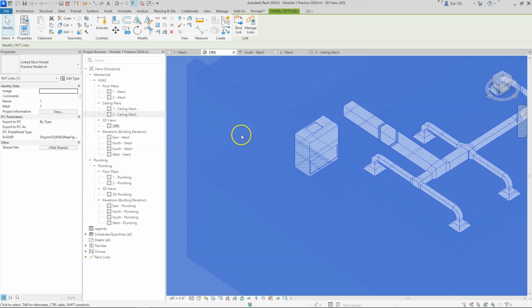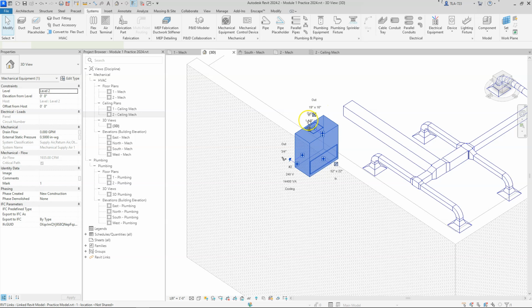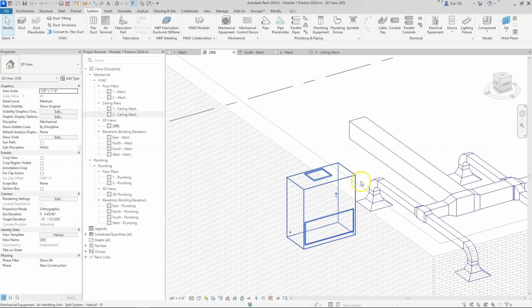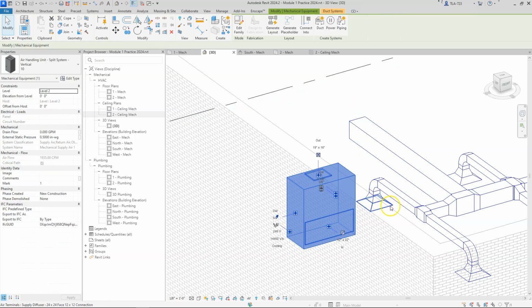One of the options that we have when we're talking about connecting into things is a tool called Connect Into, of all things, right? And we don't get this with every object type. For example, if I click on this trunk right here, I don't get Connect Into in my ribbon, but I do get it when I select either a diffuser or the HVAC system itself. So it has to be a non-duct item, I guess. But you'll see right here it has this Connect Into tool.